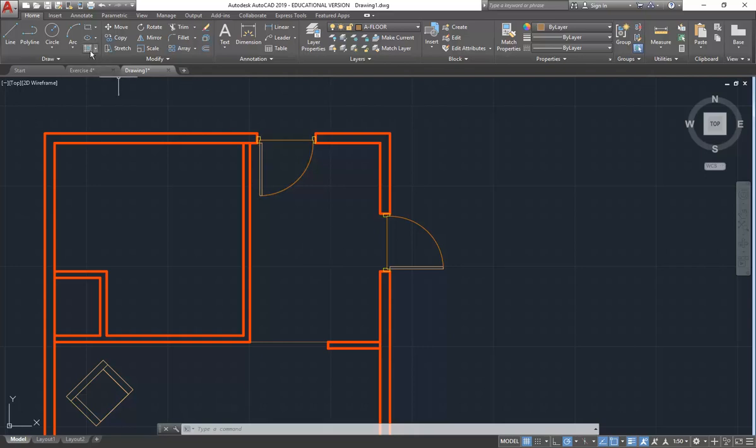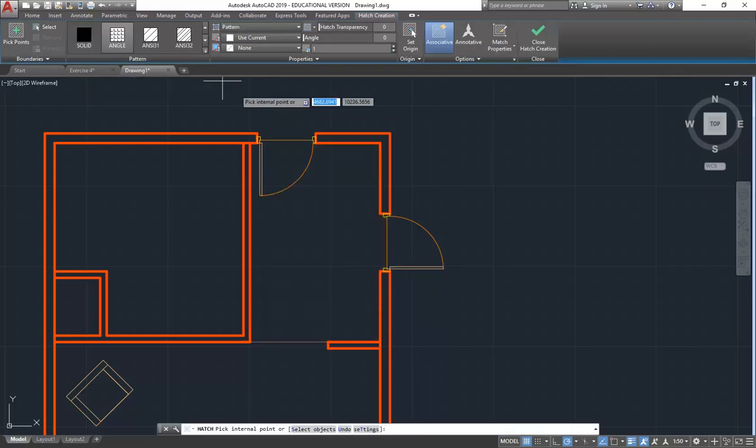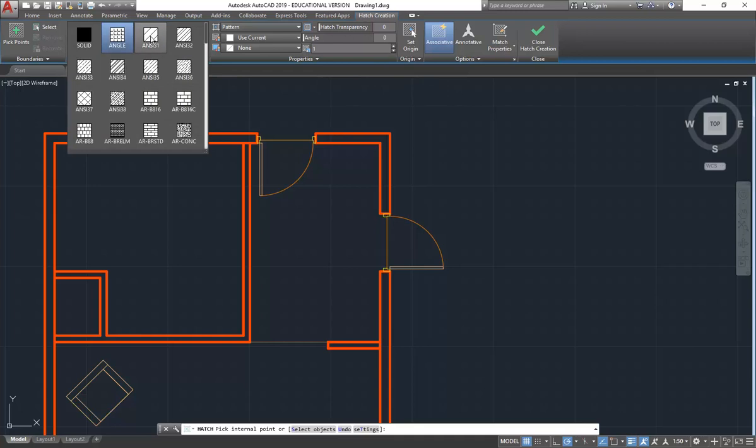So I'm going to click on the hatch button up here. And then I'm sure it would have said use one of these like ANSI 31, and then you can put the settings over here. That works, but to use those patterns that are very simple, like these that just have a single line that's repeated, and this one, any of those repeated single line hatch patterns, and this one even with the double cross hatch, they of course all work.